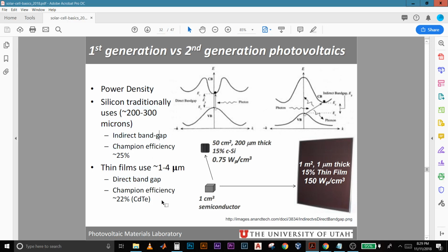And there are obviously other advantages from thin film, like a big reduction in weight. One of the important factors in designing solar panels is the power generated per area or per weight, like how many watts per kg the device is.